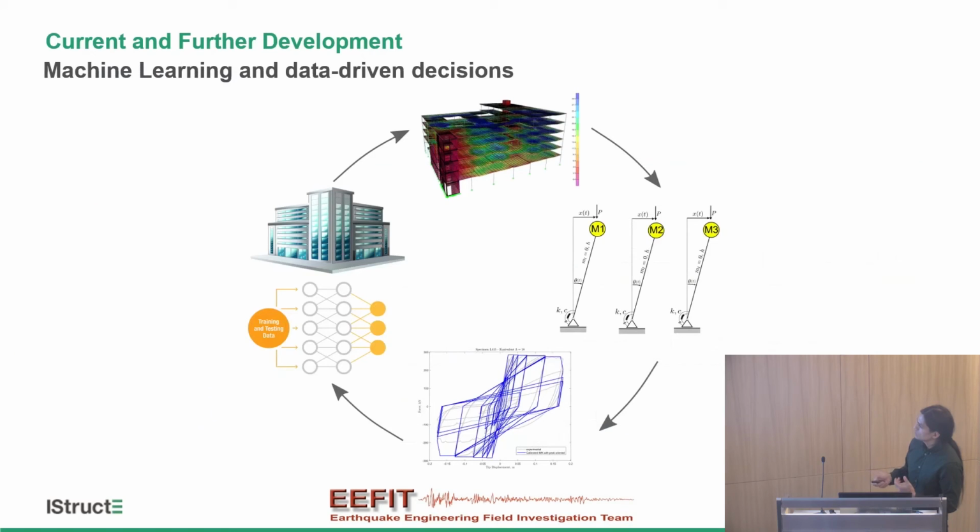And just to give you a hint of the kind of things that you can do with this kind of sensors, so far most of the sensors that we use for structural health monitoring are what I call passive sensors. So basically a sensor that is only capable of performing one task. So you go there and you just retrieve a piece of information: temperature, humidity, acceleration, strain, or whatever you need. But the possibility of sensors like this one is that we have a tiny computer embedded on it, so you can perform tasks on the fly.